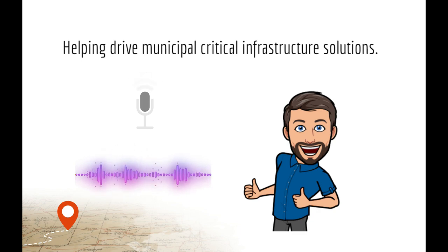Monitoring your system with a high-resolution transient pressure sensor would be a step in the right direction. This data will help calibrate the surge analysis later on. You may be surprised at the other benefits as well.